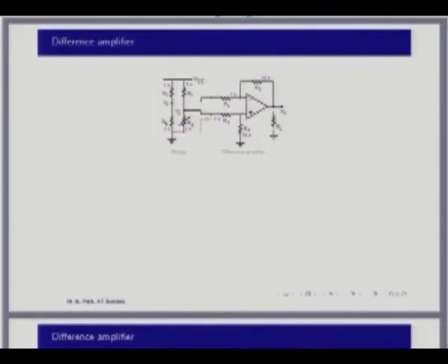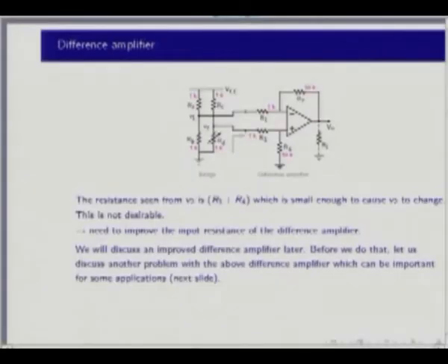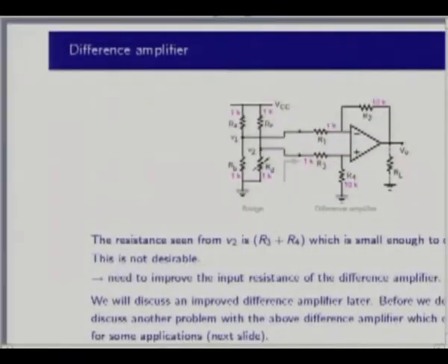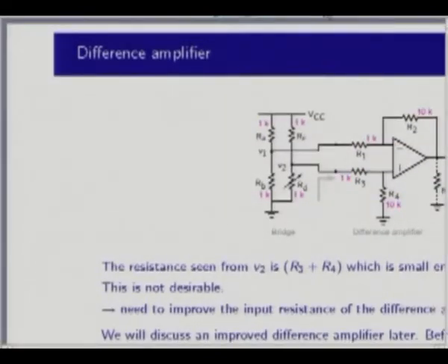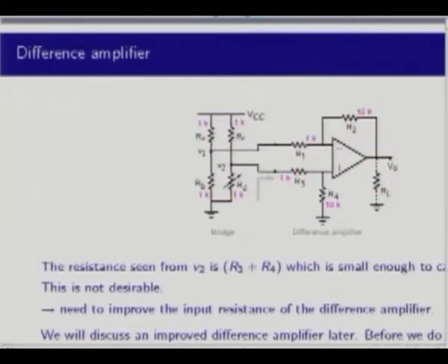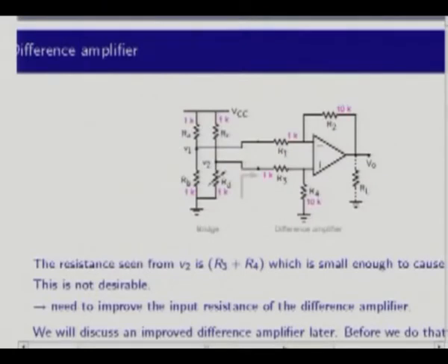Alright, now let's get back to, okay, let's put together our sensing mechanism, this bridge circuit and the difference amplifier, and see what happens. Okay. So we see some problems. If I do that, there is this V2 minus V1 that this circuit is going to amplify, and since this circuit only amplifies V2 minus V1, that is exactly what we want.